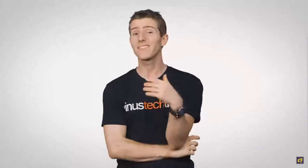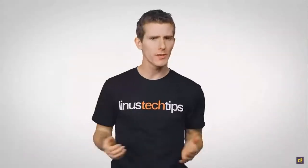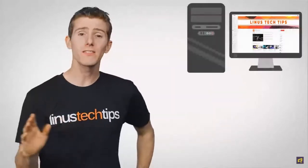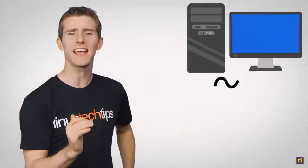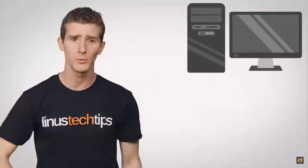AC power also gets interrupted briefly every time it switches direction. You can see this if you've ever watched a high-speed video of an incandescent light bulb connected to a regular old AC lamp. So it'll flicker many times per second according to how often the current changes direction. So that's 60 times in North America and 50 over in Europe. Now this is fine for a light bulb under normal conditions, as your eyes probably won't even notice this sort of flicker. But sensitive electronics need a constant supply of power and won't take kindly to small interruptions, as their internal logic depends heavily on maintaining very specific voltages, which you can't realistically do with AC.